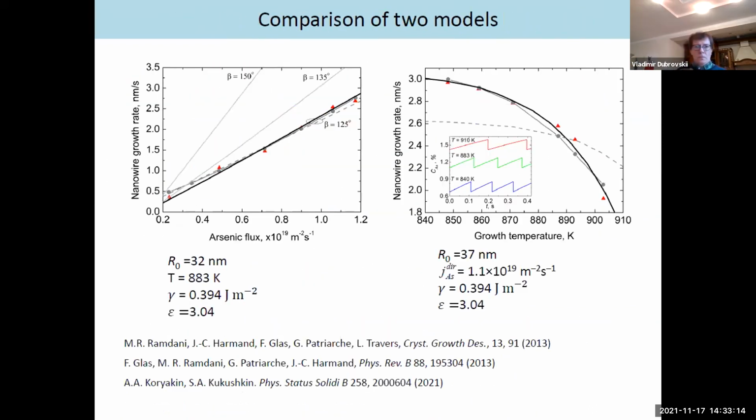What I maybe add is that I've been modeling the statistics of the growth of Wurtzite layers, and the paper is nearly finalized. I cannot really get one single value for this edge energy, but I also tend to find larger values than what I estimated in the past. So maybe closer to 0.3, 0.4 as you find. So that's very interesting to me.